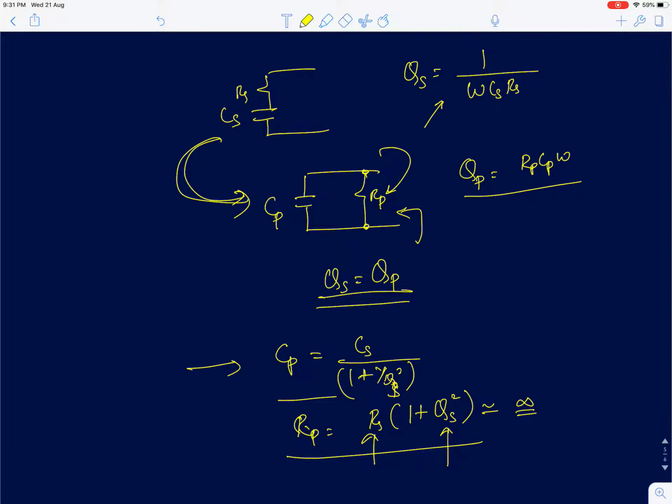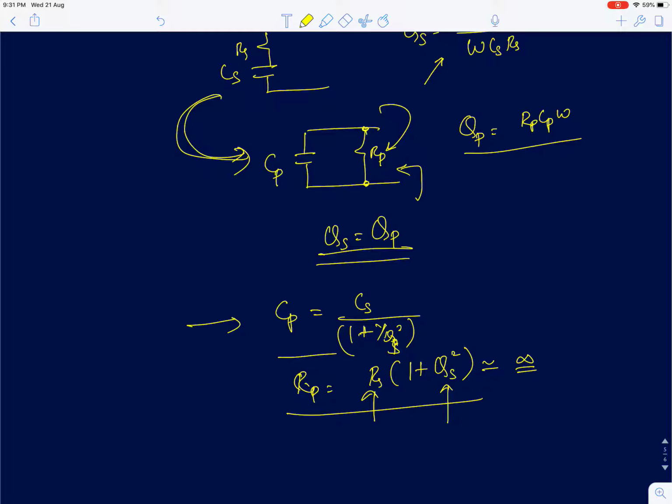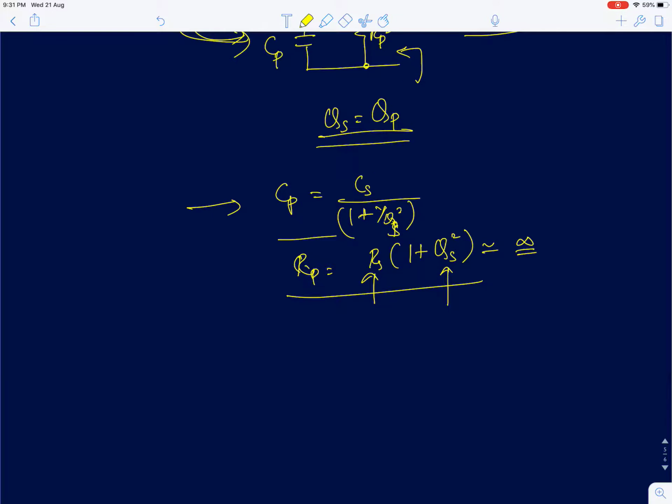Okay, so that's all about capacitors and non-ideal capacitors, and how to model or how to define Q for these non-ideal capacitors. And we will be using the analysis of non-ideal capacitors probably when we are analyzing RC circuits or voltage regulators, or even in RF circuits, when you are analyzing digitally controlled oscillators, LC oscillators, where normally you have a capacitor bank. So your frequency is tuned in this fashion. You will have a single inductor and a bank of capacitors which are turned on and off to get the desired frequency of oscillation. In that case, the switch resistance will come in series with the capacitor.